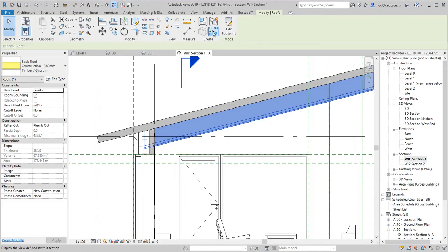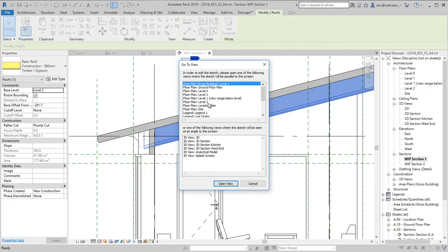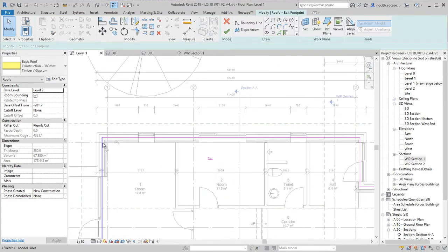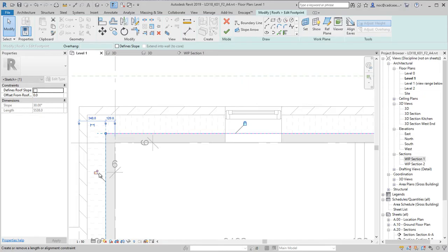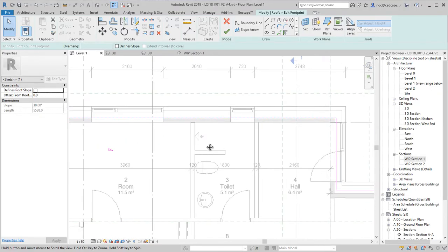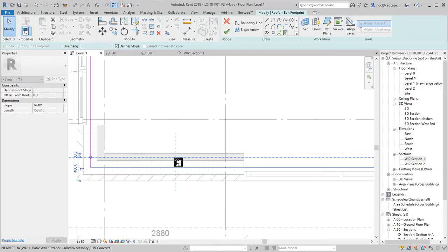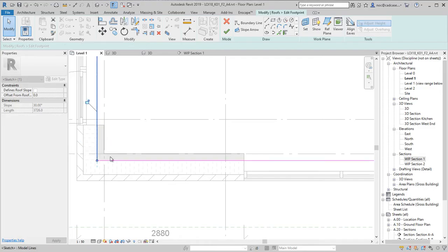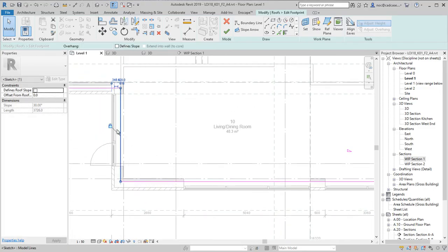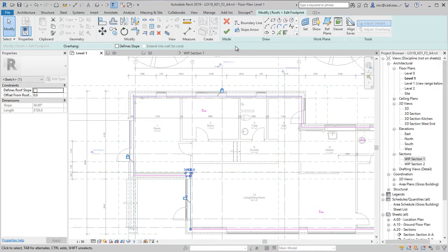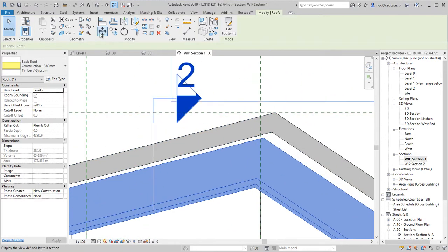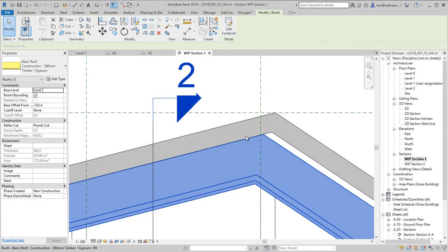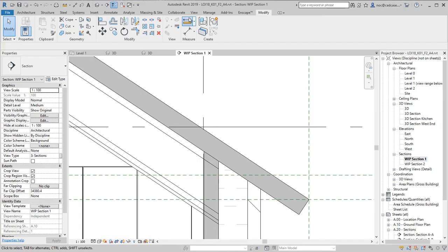Just a small note here. Remember that we have moved our external facade, so in accordance to what the original idea was with the roof, maybe you have to change the roof first of all, but we're not doing that now. What we need to do is to adjust the boundary of our roof so that it is at the back side of our inner wall. That will make our model very consistent, and that will give us, for example, the correct amount of insulation and so on. Again, there's a small adjustment that we need to do here now.